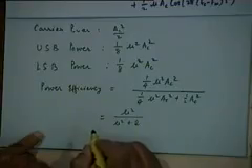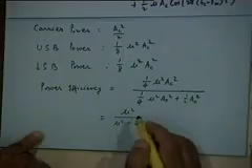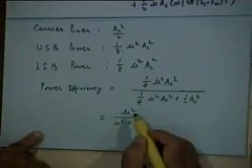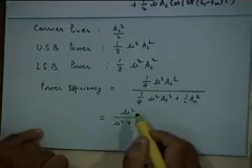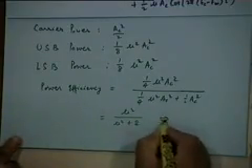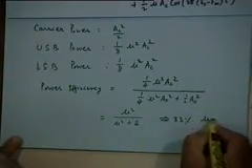Right. And therefore, that is the power efficiency you will have for a modulation index of mu. And what is the best power efficiency you can have? It will be obtained by mu equal to 1, when you take mu equal to 1, right. And what is the power efficiency there? So, 33% approximately for mu is equal to 1.